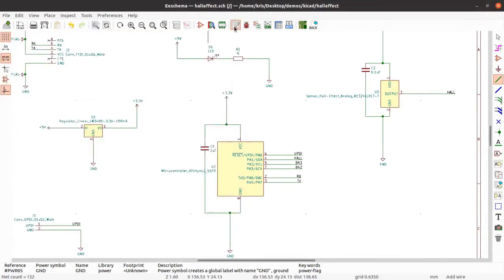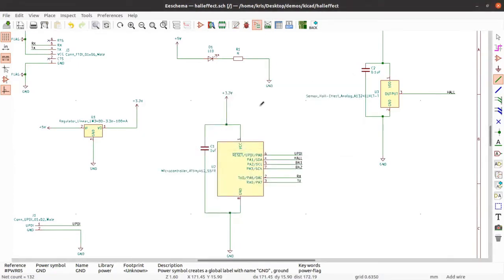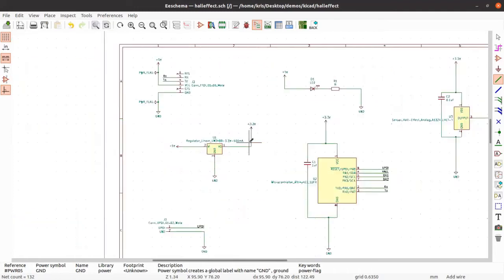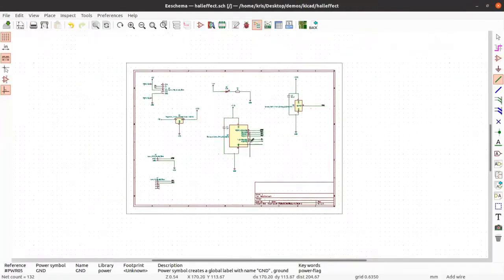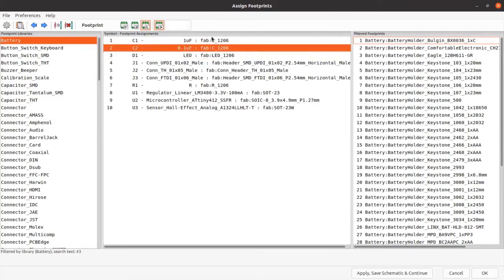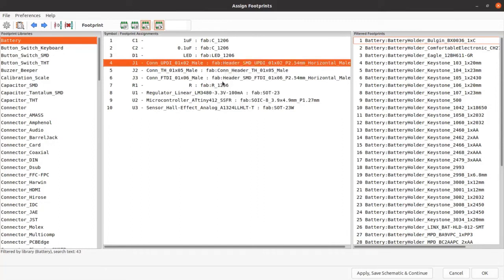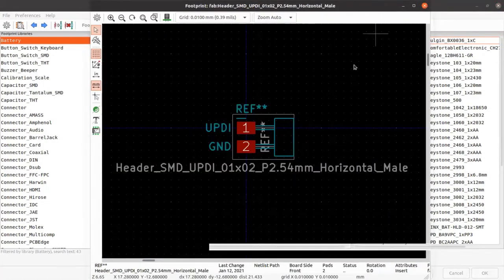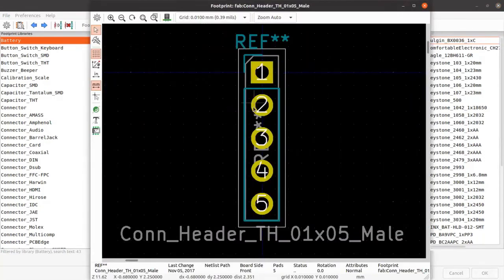No errors. And then as for the mappings, we can check. All of the Fab library parts already have footprint mappings. Yeah, here we go. So you see all the symbols are actually mapped to specific footprints. Here we have those. Then for the through-hole one, we have this.